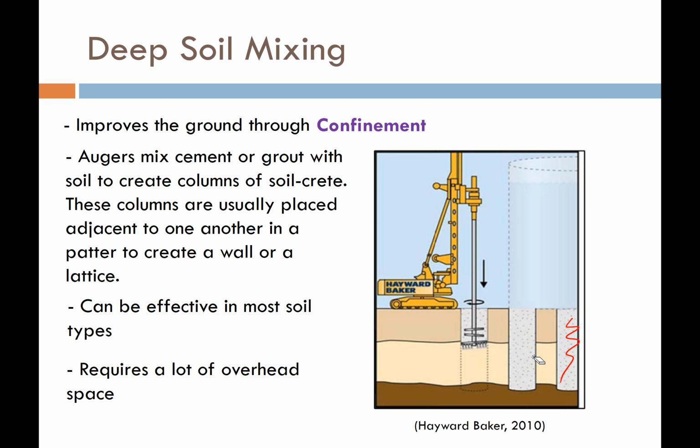Think of it like a blender that we're lowering down into the soil, and it's turning. As it's turning, it's pumping a grout mixture into the soil and mixing it all up to the point that we get a very nice, uniform column of soilcrete. And it's typically not very high strength.